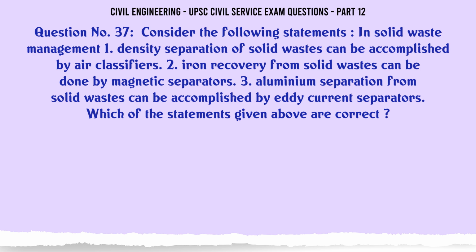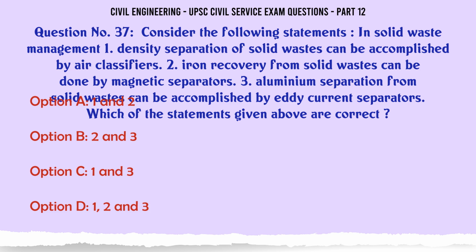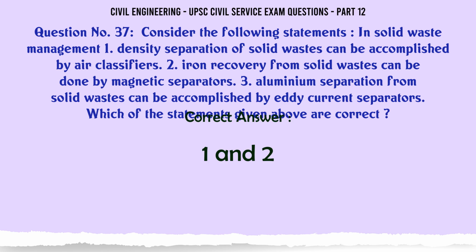Consider the following statements in solid waste management. 1. Density separation of solid wastes can be accomplished by air classifiers. 2. Iron recovery from solid wastes can be done by magnetic separators. 3. Aluminium separation from solid wastes can be accomplished by eddy current separators. Which of the statements given above are correct? A, 1 and 2; B, 2 and 3; C, 1 and 3; D, 1, 2 and 3. The correct answer is 1 and 2.